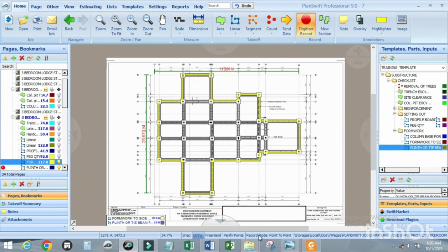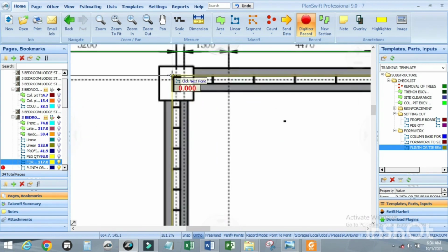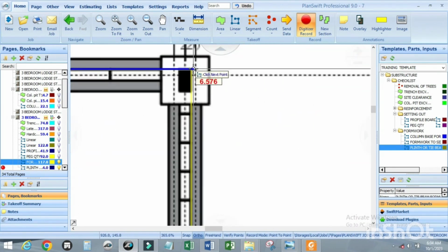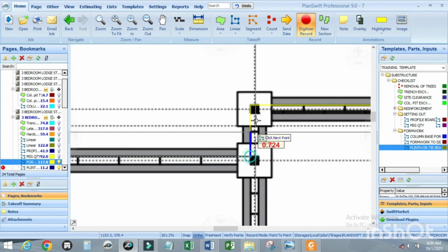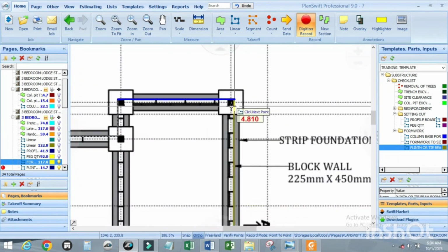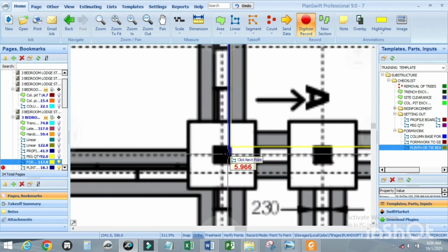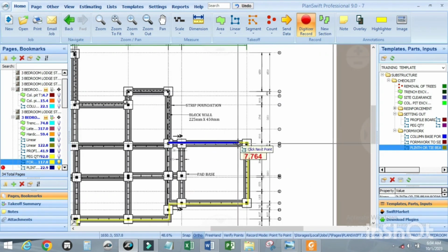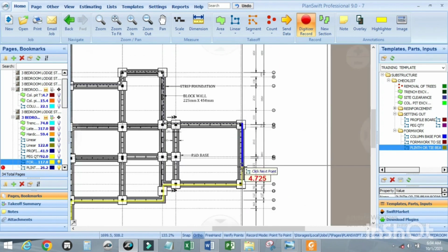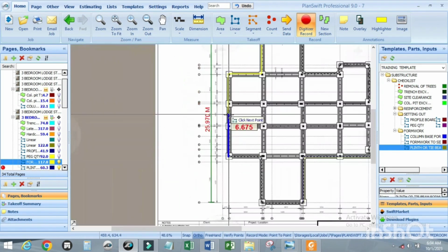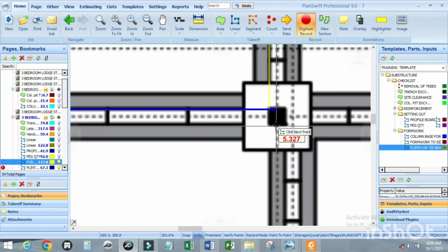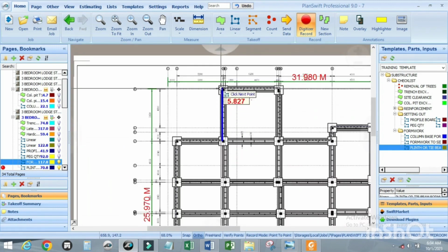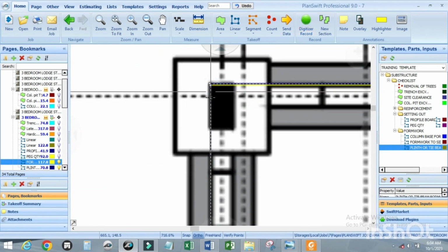Okay, the record mode is point to point mode. We have to trace the formwork to oversite concrete. Trace it on all the walls in foundation, but let us use only the external wall. Escape.